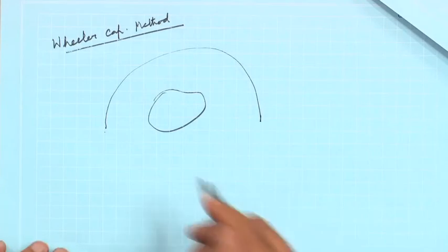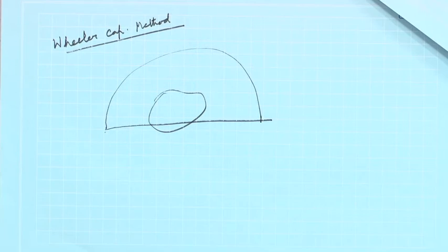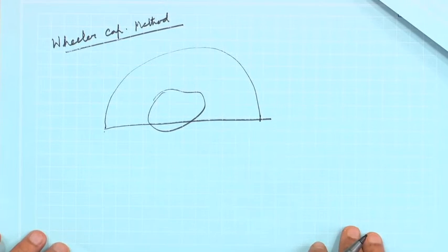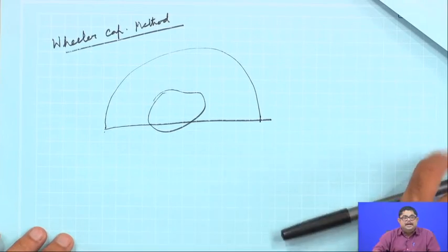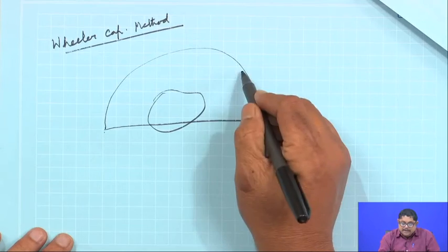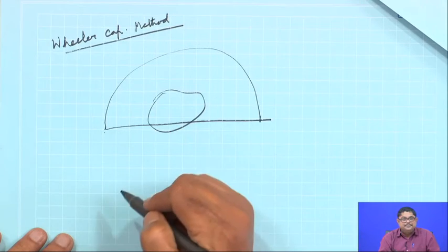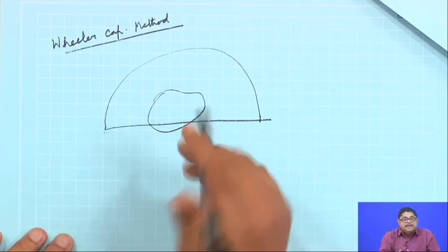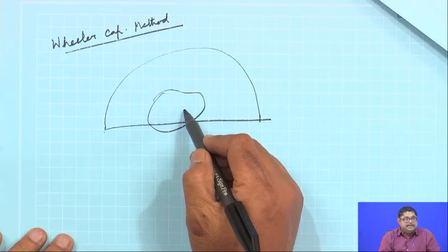Now, what Wheeler suggested for a small antenna is that you put a metallic shield over the antenna. He called it a cap, because if you have a planar structure, the cap will be something like a sphere or a hemisphere. You put a cap on that. So, what will happen? The radiation will get stopped, but his assumption is the loss will remain the same.